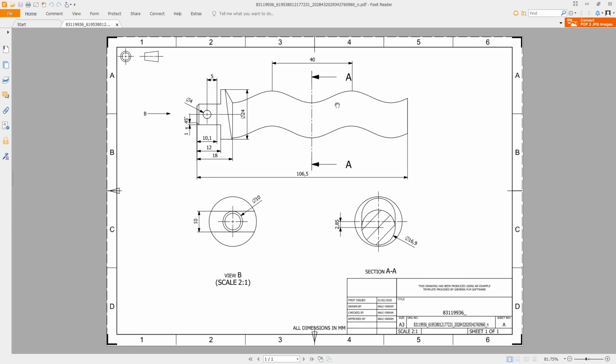So first we view the shape of this. There we show the curvature of the round shape. It is the main important thing, but how can we create it like this? I'm using the simplified spline and using the curvature. About this is okay, there we can read the full length, its pitch, its sizes, etc., and here is the displacement of the round bar in zigzag shape. This is 2.85. So now let's start.